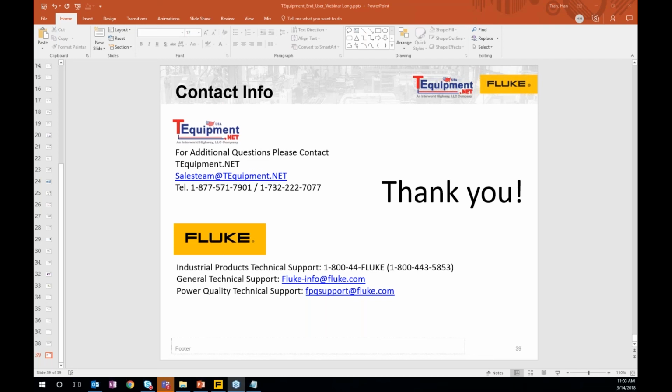Okay, well, here's the first question. How can you get torque and other mechanical outputs from just measuring the voltage and current? Oh, good question. Our tool, the Fluke 438 Series 2, measures by using just voltage probes and current probes, and it uses current signature analysis from the current and the voltage that it measures to determine what the torque is. So it uses a very complex algorithm to figure this out. So you don't have to make any physical measurements at the motor itself.